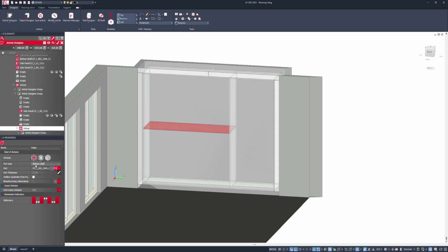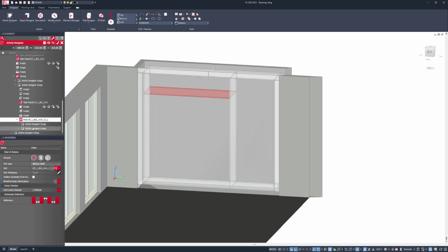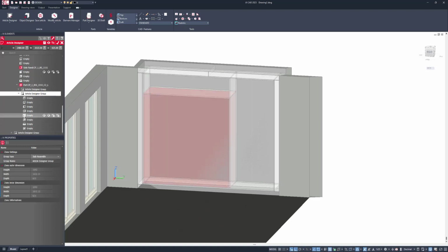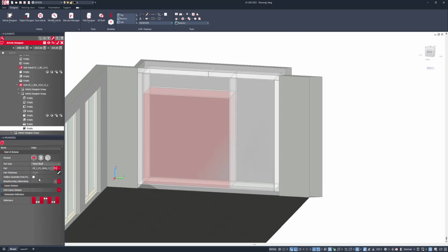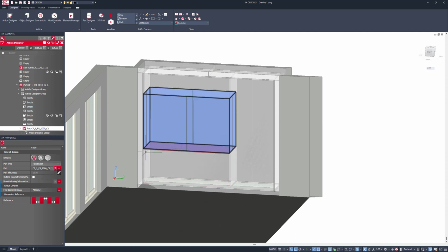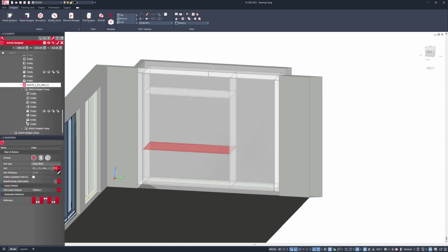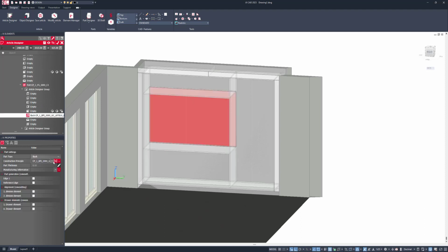And actually, if I change this to be a bottom shelf, I can specify that this should have some lights in here, which I like the idea of lighting up my products. So I'm going to go in here and say that this should be 400 millimeters from the underside. And then in the lower zone, I want to add in another fixed shelf, this time 700 millimeters from the bottom. So that now gives me two zones, and what I can do now is go into the upper section of that zone and add in my back panel.